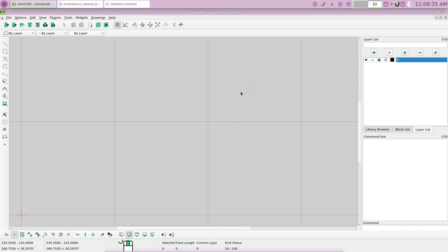Okay, so once we've opened up our LibreCAD application, again, you will notice these buttons all along here. You may have seen them before. If not, you will see them here. This is your layers list, and you have the ability to work with your layers here. And every drawing is built in layers, just like any image or photograph that you might make in an image editing program like GIMP. You do work on layers, and CAD systems are no different. Different layers for different portions of the drawing.